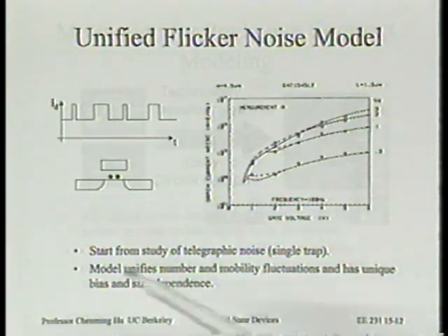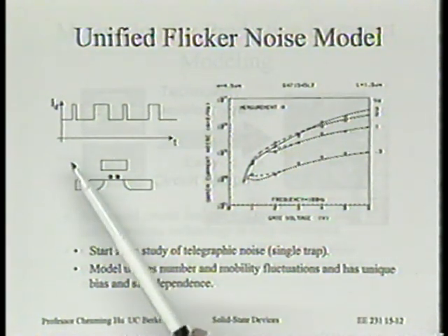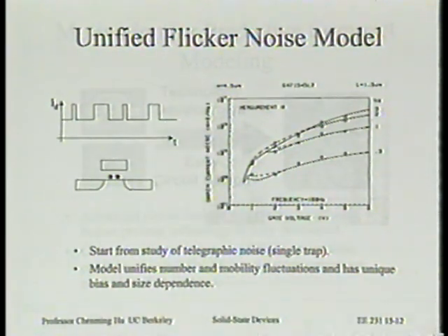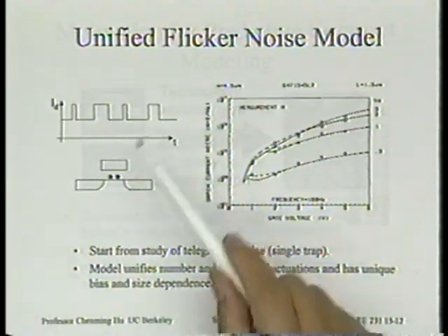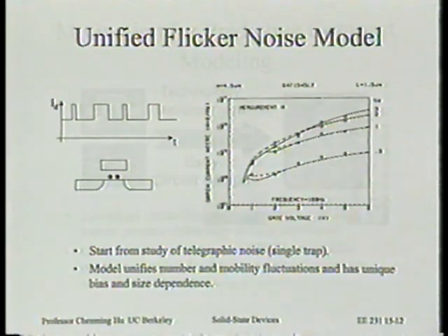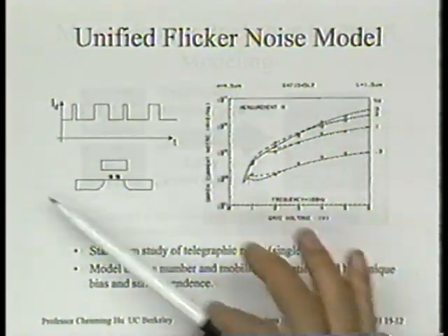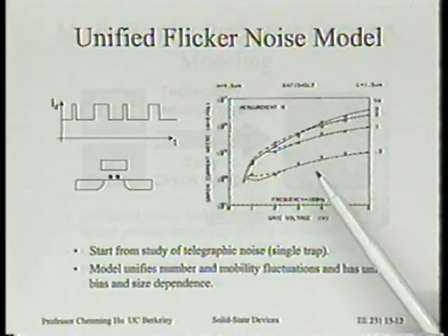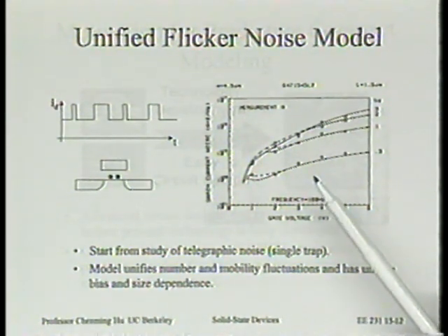It started with the concept and parameters that one could determine from telegraphic noise, and indeed was determined from telegraphic noise in terms of research, but in terms of getting the model parameters for actual production technology, engineers wouldn't go to telegraphic noise. They would just try to fit the model equation to the actual measured 1/f noise, of course, right?